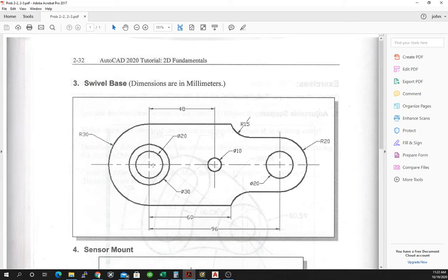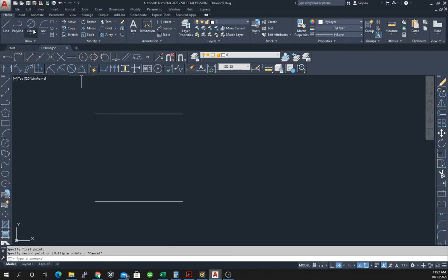All right, so now let's put these circles in. So these circles will be actually 30 up from this lower edge. And one will have a diameter of 20, one will have a diameter of 30 for the two center circles. So circle diameter.